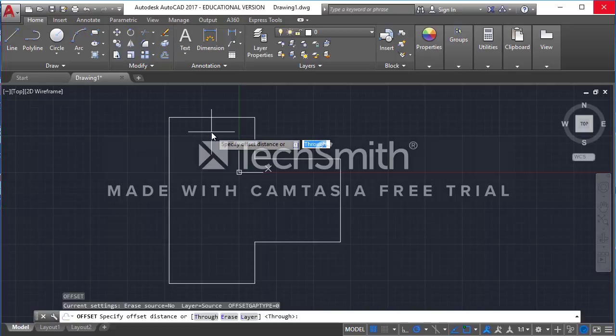distance, okay? So for this class, we're going to just say that our exterior wall is 6 inches. If you get into technical terms, that wall thickness could completely vary. It could be anywhere from 4 inches all the way up to a foot, 14, 16 inches. Walls could be very thick. Interior walls that you might have in your house are typically like 4.5 inches.